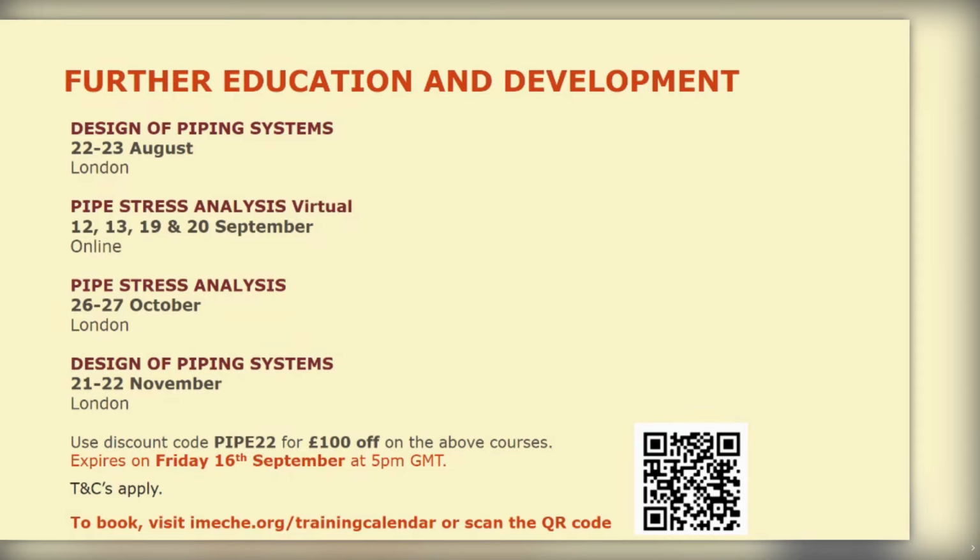The other thing to consider is that if you need to comply with the CE marking Pressure Equipment Directive in the EU, then following the EN standard automatically gets you there. If you do it to ASME, you'll have to jump more hoops to get there. On the other hand, if you're trying to comply with regulation in America, then going with ASME will help. In the UK, under the new regulation since Brexit, either of those codes will comply with the pressure equipment safety regulation. So it's your choice.